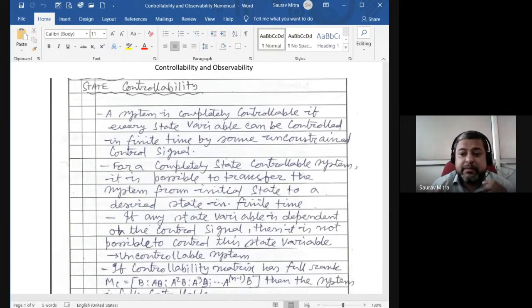Then we entered the second part. There I was giving you the system differential equation, d2y/dt2 plus 5 dy/dt plus 3 y(t) is equal to something of dx(t)/dt plus something of x(t). So y(t) is the output, x(t) is the input. If I give you this kind of system differential equation, you take the Laplace transform on both sides, then you find Y(s)/X(s). That was the first step. How can you convert this differential equation into the system transfer function? That was the first step.